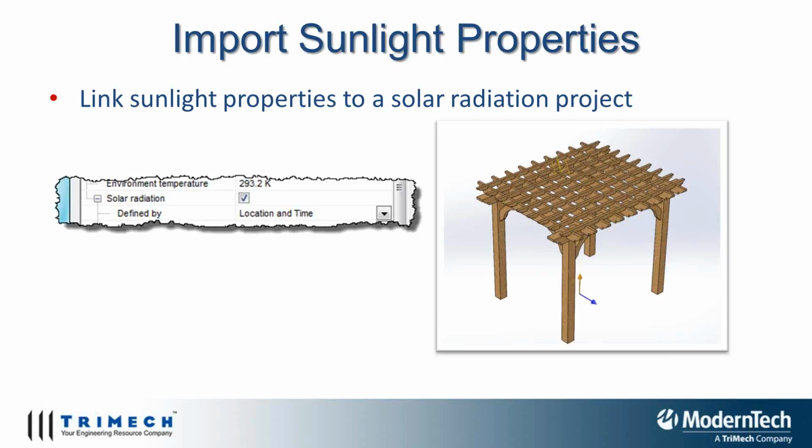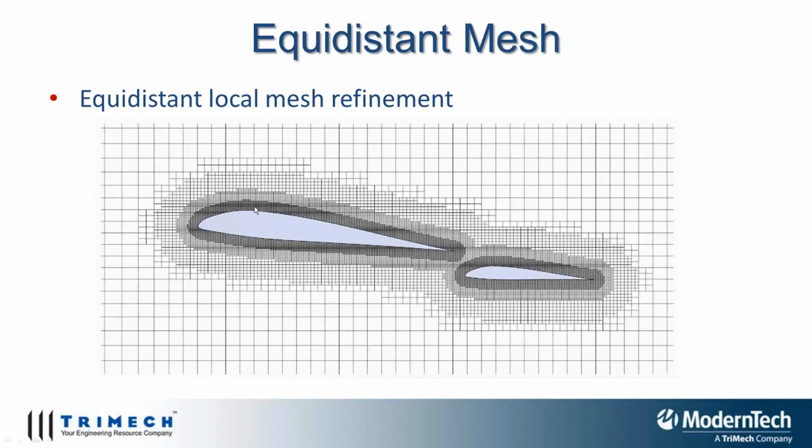What this means is, in the past, when somebody was dealing with a boundary layer problem or really high pressure gradients near the boundary of a particular geometry, in aerodynamic or high-end thermodynamic problems, users had a little bit of difficulty in modeling the really fine mesh around the surfaces or volumes of the geometry. We typically had to create a dummy geometry and then introduce fine refinements around this area.